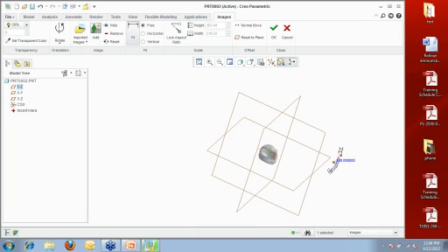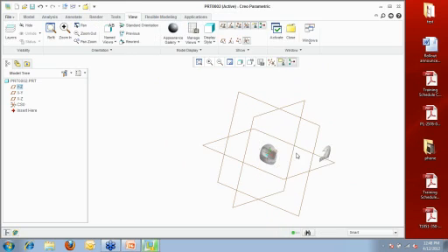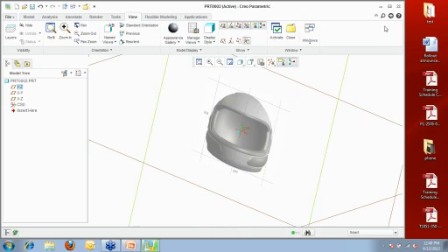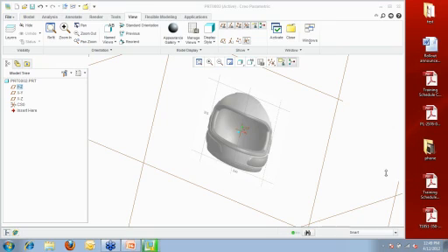So the idea behind it, now I have those, and from here you could go ahead and create curves from this outside shape to that outside shape. So hopefully that answers your question about that, Mike. But I'm pretty sure in Creo Parametric that's a default function. I don't think you can do that outside of Creo Parametric. It actually is only within the ISDX tool anywhere from Wildfire 5 and back.